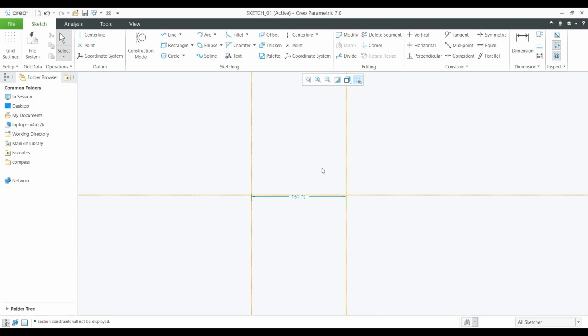But as per the drawing, we need to see the constraints. If you want, you can select it here. If you don't want, you won't be able to see them. Now again, I uncheck the dimension. See here, my dimension is also gone. But I want the dimension, because if we create any kind of 2D drawing or any kind of 3D drawing, we need a dimension. So we need to show the dimension.